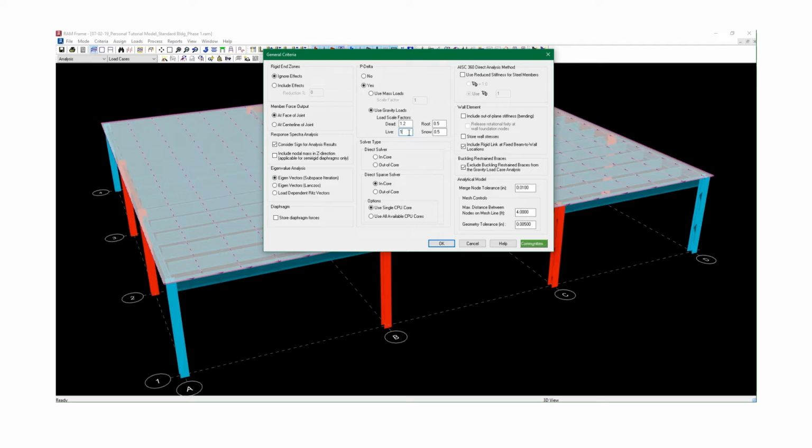It's individual load cases. So it's a linear, first order linear elastic analysis, essentially, that's being applied and modified a little bit with the stiffness matrix, modified a lot with the stiffness matrix. And then those individual load cases are subsequently combined using the principle of superposition.